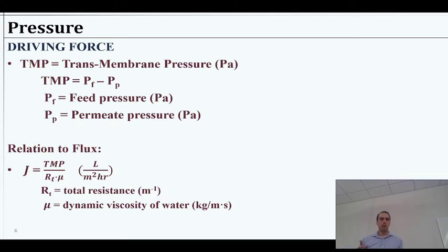And what we call that pressure in the context of a membrane would be transmembrane pressure. You can actually discern a pressure drop from before and after a membrane because it has consumed some of that energy to force it through. So we will talk about pressure drops, or this transmembrane pressure, a delta P. For our sake, I'll typically refer to it as TMP, and I'll be defaulting to pascals for those units so that we can use a few of these equations.